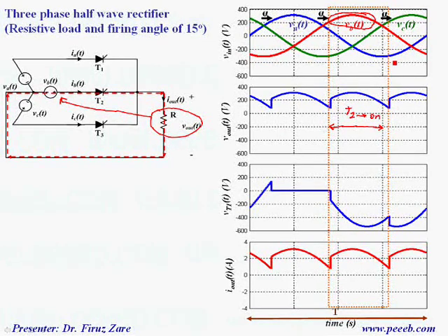Then it's the same scenario for the next cycle. That means the output voltage is phase B and is decreasing just at this point. If we apply another gate signal to the third thyristor, then we can turn it on. And because phase C is greater than phase B, the voltage across the thyristor will be negative.